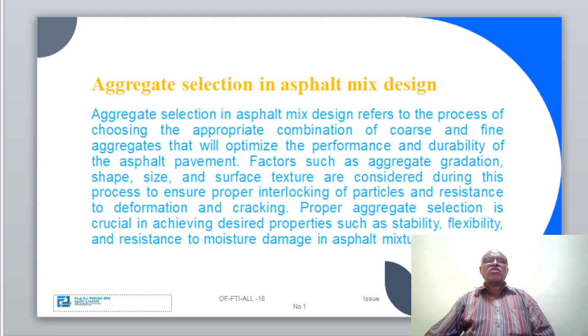In addition to these factors, the moisture content and specific gravity of the aggregate must be carefully considered during mix design to achieve the desired proportion of the final product. By carefully selecting and evaluating the aggregate components of an asphalt mix, engineers can create a durable and high-performing pavement that meets the required specifications for the construction project.